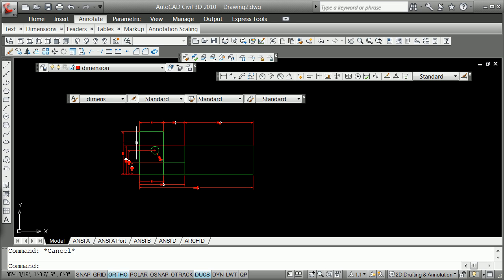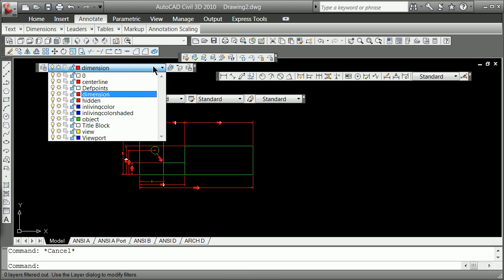So I generally don't use hatch. I use bhatch because it goes along with the command bpoly. Very often it's a nice idea to make a layer particular for that, the hatching. So I'm going to go ahead, I've got the dimension here. I don't really want to look at the dimensions right now.